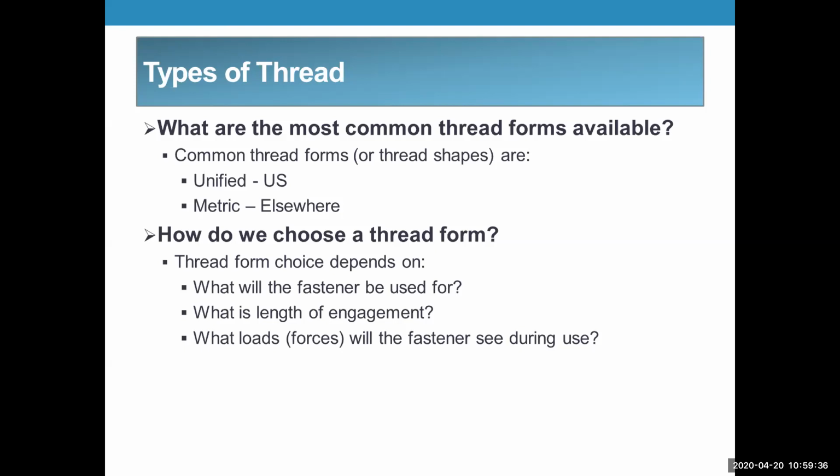So it's friction plus the clamping force. I know it's maybe a little hard to grasp at first, but it's not going to transfer the torsional load from the force applied at the middle of the beam and the reaction at the end that creates that torsional moment. It's not going to be there when it's bolted or riveted.